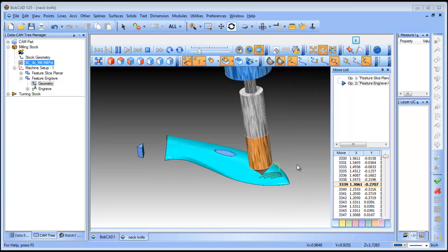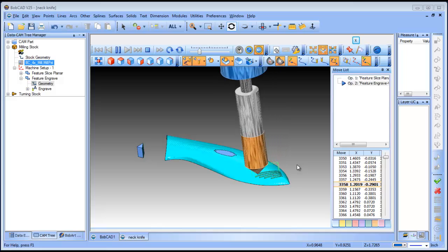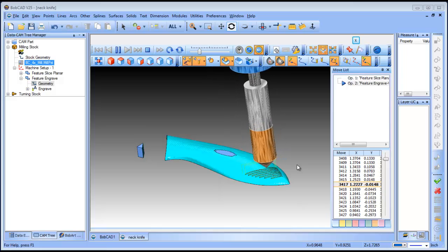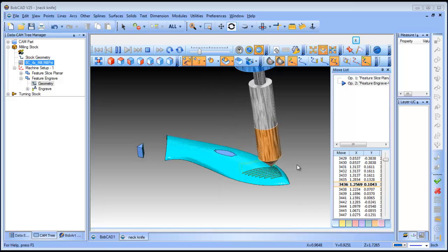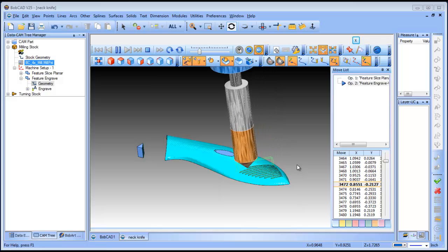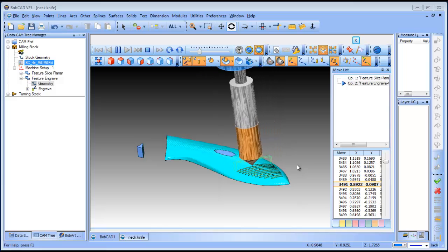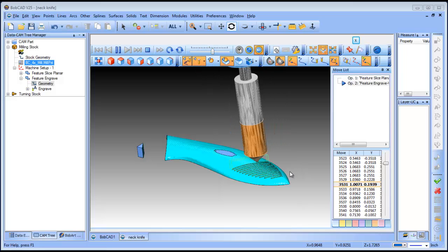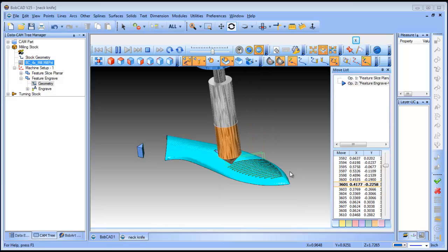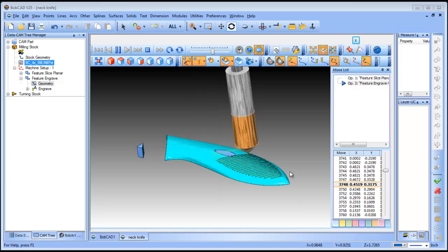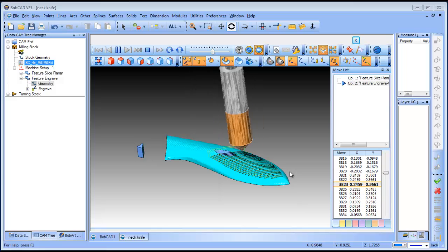Now, you can project your toolpath down onto the surface. Because I used the crosshatch pattern in order to generate the geometry, it will follow through in the order that it was created. Sometimes you may just choose to use your toolpath boundary and run a planar toolpath with an engraving tool like this, or a V-tip cutter, which would give you the same result. Again, this is one example of how you can project toolpath, or types of toolpath projections, and the way that that works.